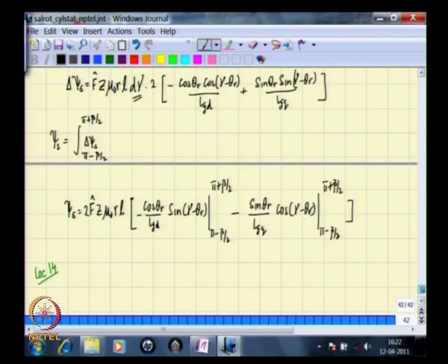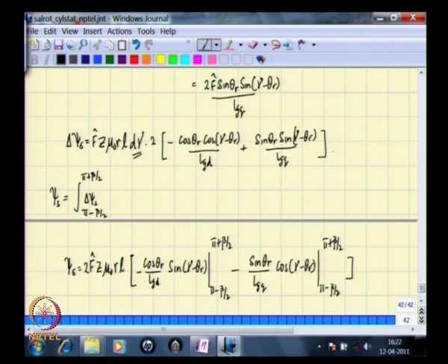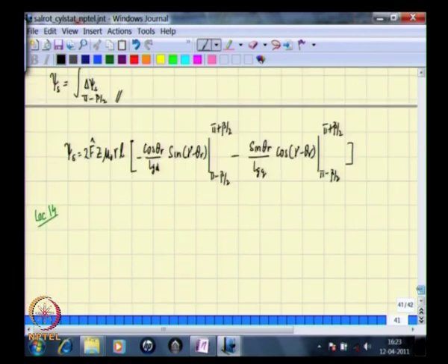we perform another integration over the span of the winding, and when we did that, we have an expression here. This expression was the flux linkage of the elementary coil, and then in order to get the flux linkage of the entire winding, we integrate over the span of the winding being denoted by beta, and we got psi s equal to this much. Now let us try to simplify this relation and proceed further.